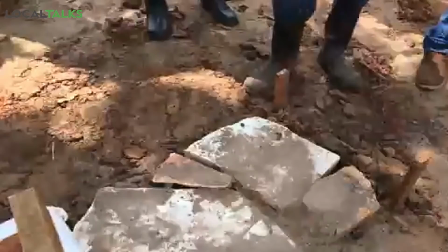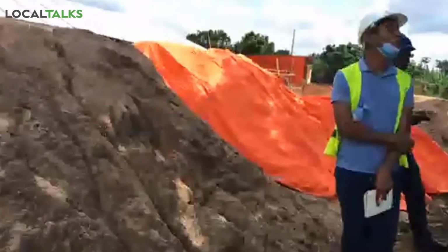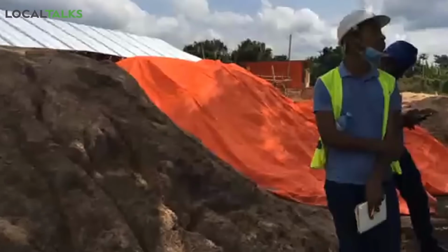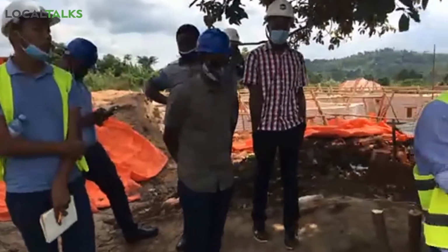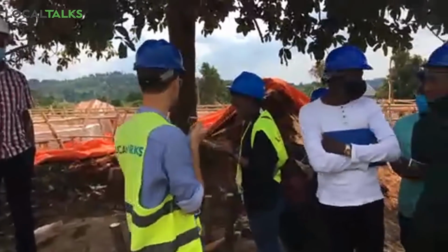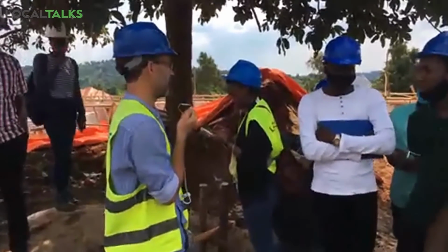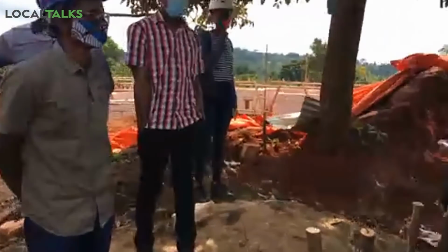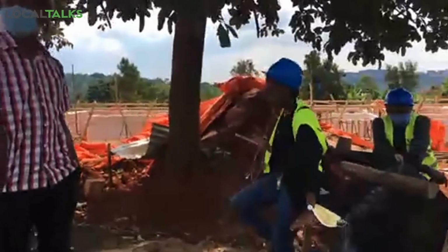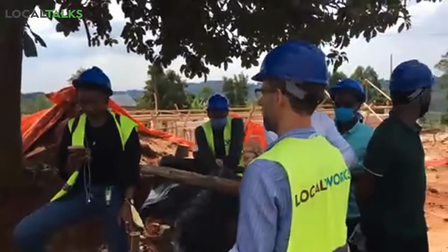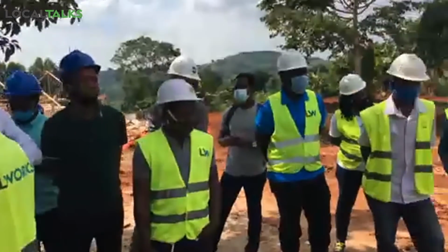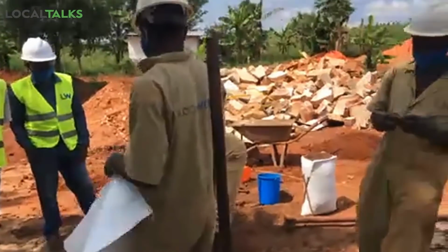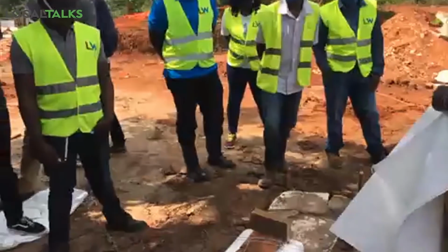So we are really happy that we have managed to estimate the cubic meterage of walling so precisely that our building levels ended up working out really well with that. We have not carted away any material at all. And the little bit that we did cart away, we just carted to the football pitch where we had a need for additional filling. So my first answer would always be: try to use the material that you have on site and try to dimension it correctly so that the building level is chosen smartly.